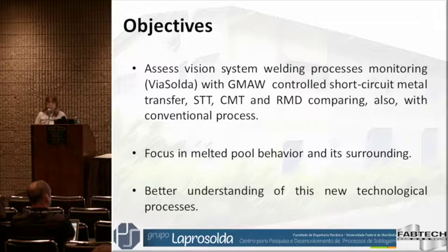The objectives of my work specifically are to assess my vision system, the prototype that we built, with these commercial controlled short circuit MIG welding processes, SCT, CMT, and RMD, and to focus on what we can see of the pool behavior and the surroundings, and hopefully get a better understanding of this process.